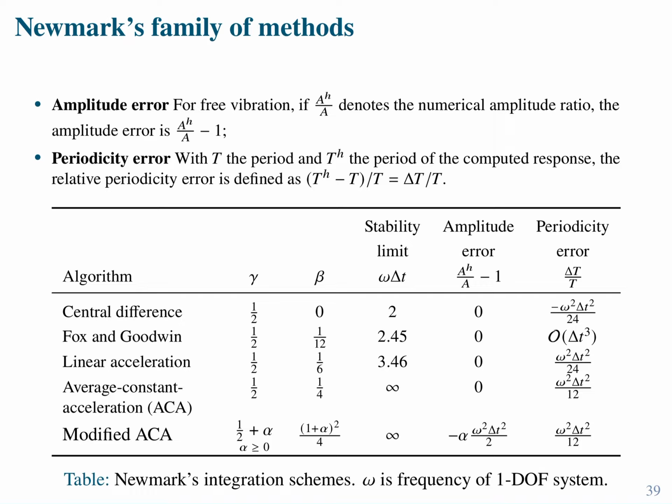In reality, the times in my group where we had to pick a method, we went for the one that we knew was working the best, and then we just kept to that until you face issues and find that there are some problems with the method. For instance, we have done some work in dynamic fracture propagation. We tried the Newmark family and we tried the trapezoidal rule, and we see that when we are propagating a crack in the dynamic setting with inertial effects, using a very fancy enriched formulation, we get oscillations in our so-called dynamic stress intensity factors. So our Newmark approach to this problem was not good enough, and we started to look into different methods. None of the Newmark family approaches actually solved the problem.